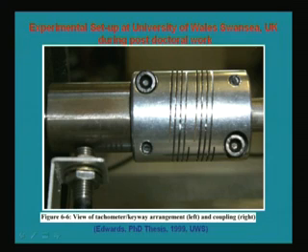And here you can see there is another proximity probe. We can have one undercut on this, so that whenever this comes here, we will get a pulse, and that can be used to obtain the speed of this particular rotor, or even it can be used as a phase reference for other signals. So now we have already seen various kinds of measuring instruments and analyzing instruments.